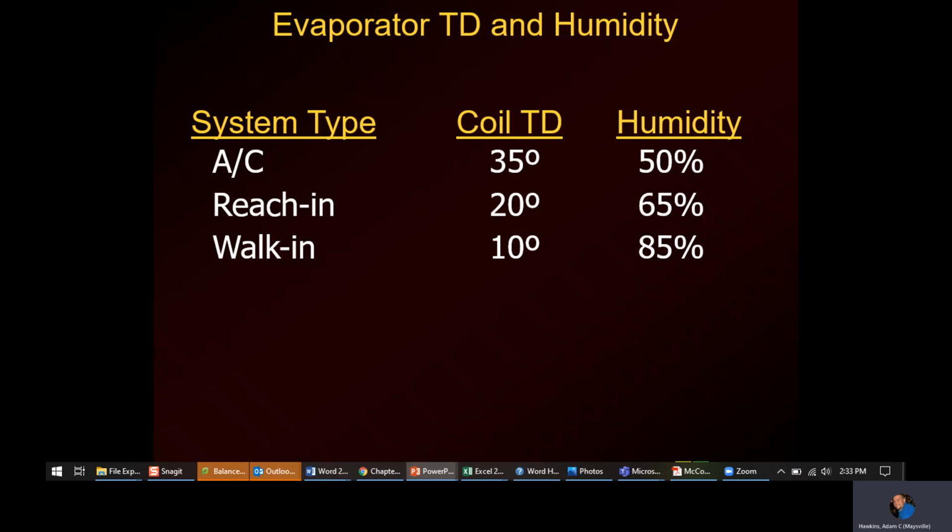There's actually a lot of information that shows that if you reduce the humidity in the summertime, when it's humid outside and when it's humid in the room, you get it a little bit drier. Now, you don't want to dry it completely out, but you get it 40 to 50%. You can actually run your thermostat higher because your temperature doesn't have to be as low because you don't feel as hot. That humidity makes everything feel damp, everything feel clammy, and makes you feel warmer.